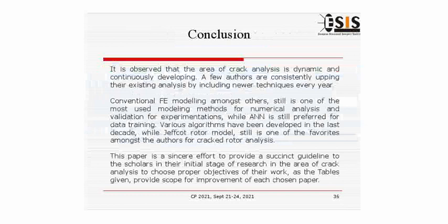Conventional FE modeling, amongst others, still is one of the most used modeling methods for numerical analysis and validation for experimentations. Artificial neural network is still chosen for data training. Various algorithms have been developed in the last decade, too many of them. While Jeffcott rotor model is still one of the favorites amongst the authors for cracked rotor analysis.